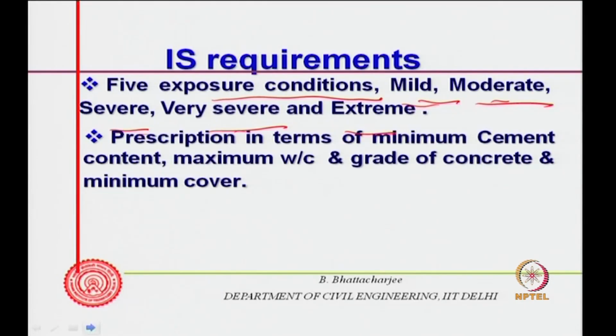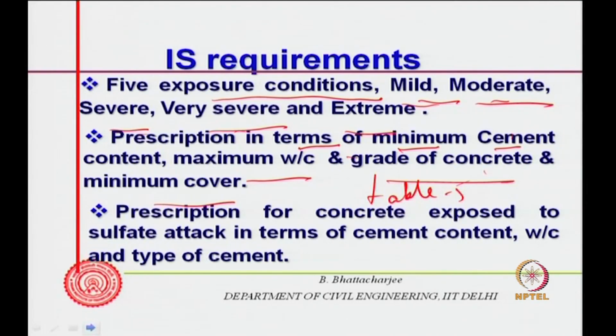For example, the condition mild is an ordinary condition, not exposed to anything. Extreme would be exposed to all kinds of degradation possibility, such as the splash zone in a marine environment. It is also matching with the erstwhile BS 8110. Then it gives you prescription in terms of minimum cement content, maximum water cement ratio, grade of concrete and minimum cover. These are given in a single table, Table 5 of IS 456, and part of the table is reproduced here for your understanding.